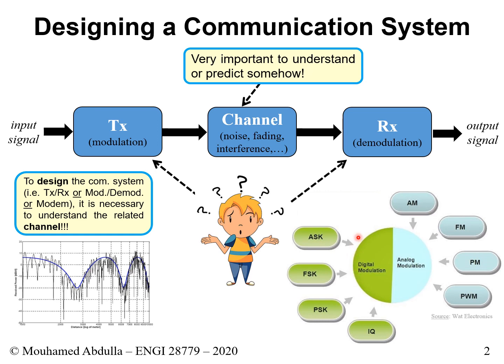And so that's how designing a communication system is. Not all modulation schemes make sense for all types of application. Say you have satellite communication, you will use one type of modulation scheme as opposed to, let's say, LTE, 4G LTE, or 5G communication, or narrowband IoT. You'll have a different type of modulation scheme. So the application and the type of channel that you consider make you decide the type of modulation scheme to use. So that's kind of the big idea that I want you to perhaps get from this slide.